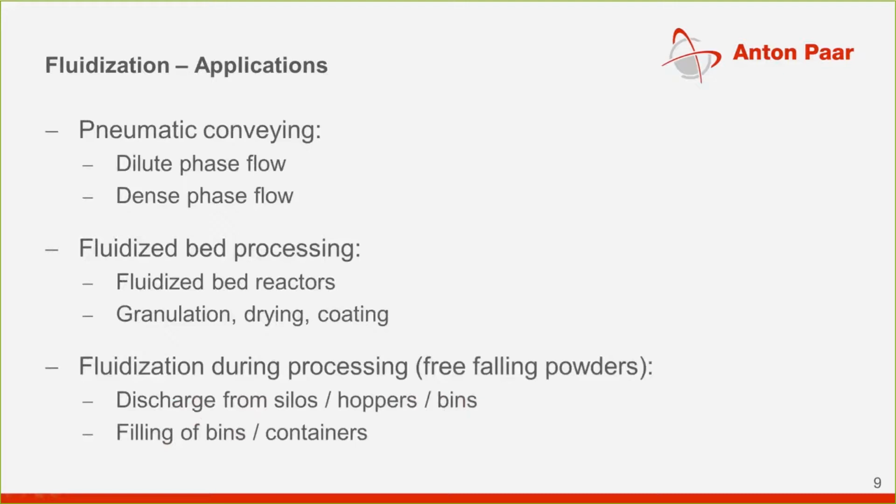But fluidization often takes place also during processing, for example when looking at free-falling powders. This is a gravity-assisted fluidization that can take place, for example, during discharge from silos and hoppers, but can also happen when a rat hole collapses.